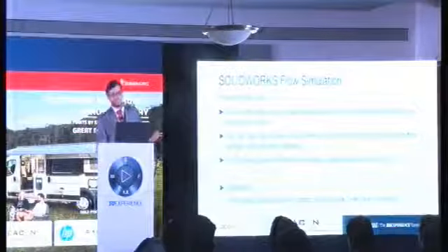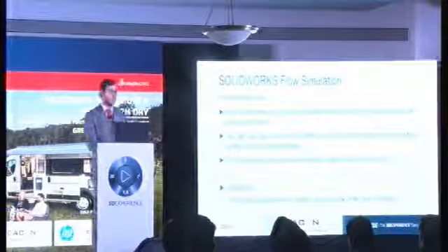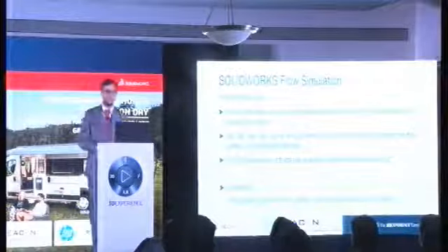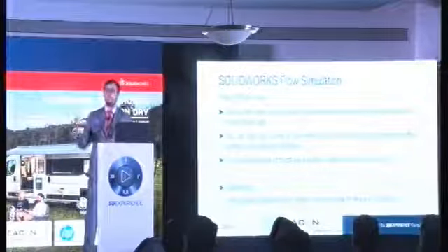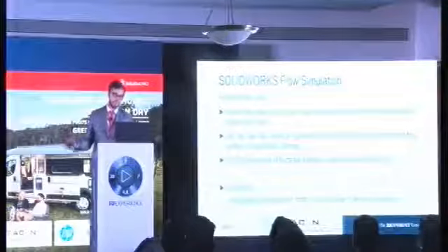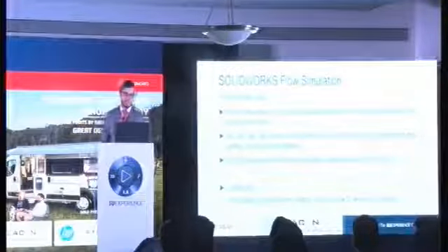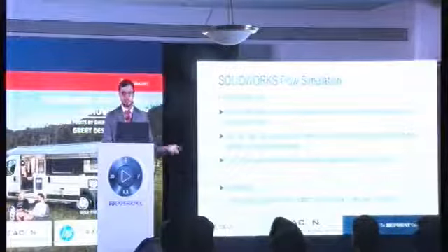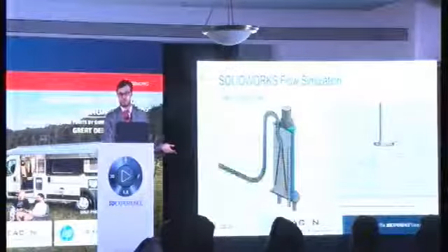We have the free surface flow. What exactly a free surface flow is: it lets you simulate flow with a freely moving interface between 2 immiscible fluids. You can use the volume of fluid method for tracking and locating the free surface. There are certain limitations, such as rotation, porous media or fans are not allowed.